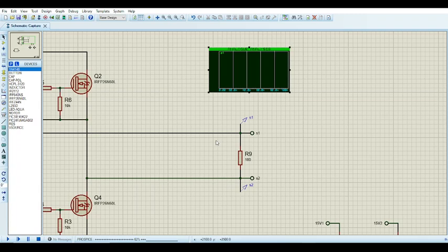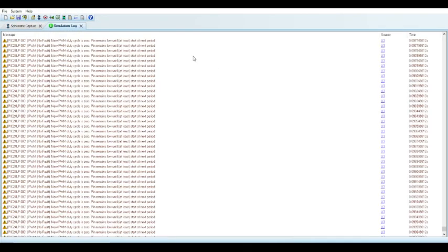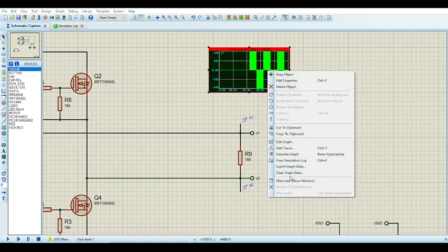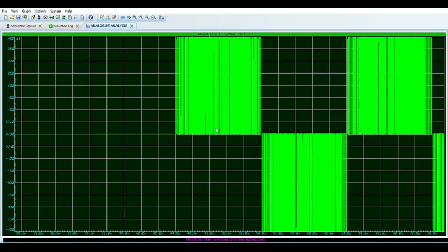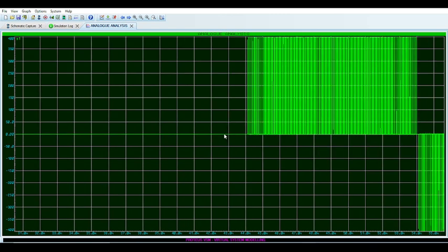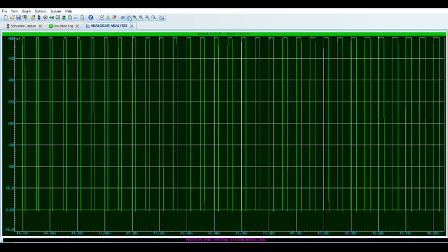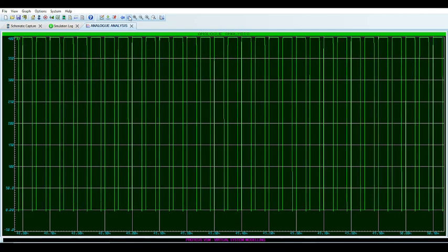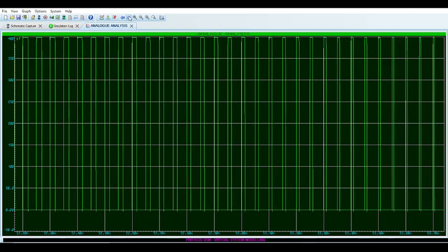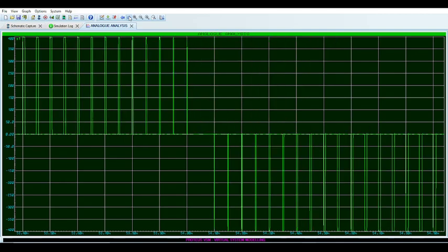So I think it simulates pretty quickly, not take too long, so it's a good thing. And also, alright, so you look at it, basically have SPWM, and you basically have a sinusoid without the filtering. It's SPWM. I'm just zooming there, so it makes a lot more sense. As you can see there, the duty cycle is changing, increasing, increasing, increasing, and it decreases back down to 0.